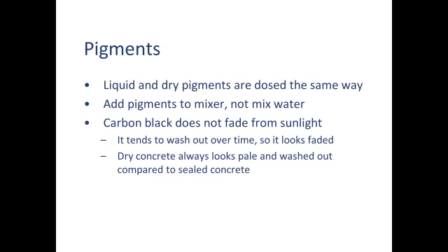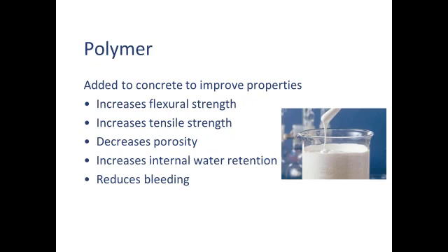That idea of adding pigment to the water comes from making bagged concrete products, say like concrete overlays that are tinted. You always have a bucket of your water and probably polymer in it, and then you add the bagged mix to that. Well, the rule of adding pigments to the water before you add your mix makes sense, but only if you start with your water and then add your dry ingredients to that water slowly. But if you're making a from-scratch mix, add your dry pigments with your sand and your rocks up front. They're going to disperse better. And I already mentioned the carbon black, so I'm not going to repeat it.